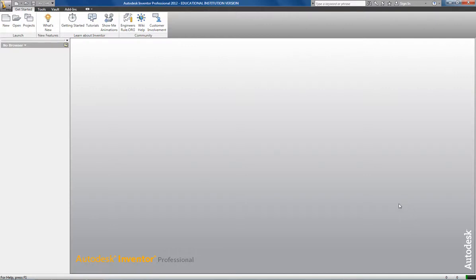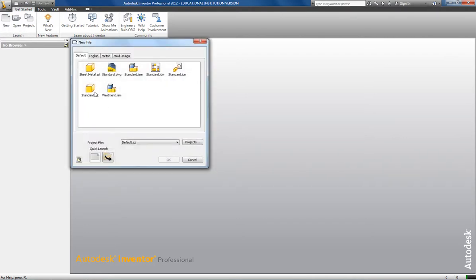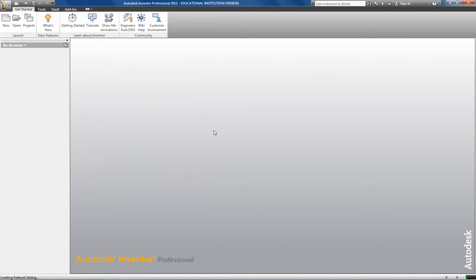Exercise P2-7, what we're going to be taking a look at is how to not only create the initial shape, but also the flat oval slot that is through there. So the first thing I'm going to do is just start a new standard IPT. And starting from the origin point, as soon as this comes up, I'm going to begin to draw the rough shape of the object.